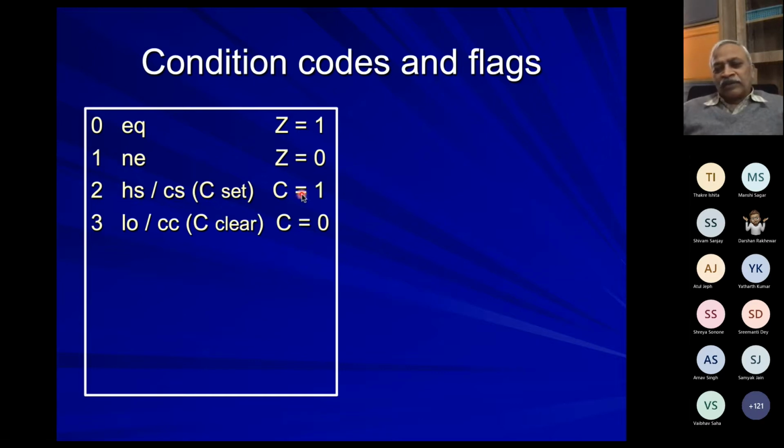Why? Because subtraction is actually being done by taking 2's complement of OP2 and adding it. So just do this mental exercise. Suppose you take a number and add 2's complement to it. What will you get as sum? What will you get as carry?